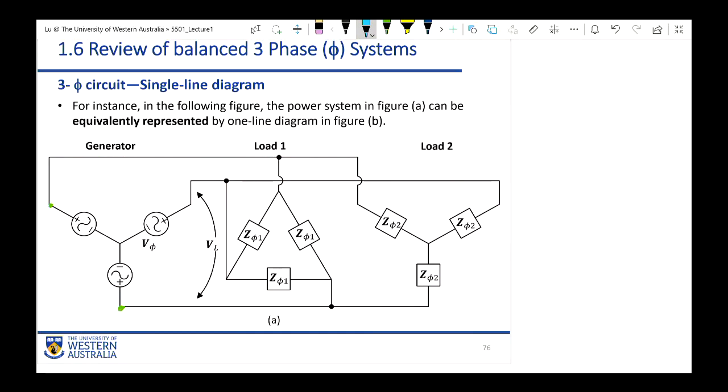So let's use one phase as an example. If the current is going up here, at this one single node in this circuit, there are only 3 connections. The blue arrow line on the left is the incoming current to this node. There are 2 outgoing branches. One is going down into node 1. The other one is going to node 2. So 1 in, 2 out.